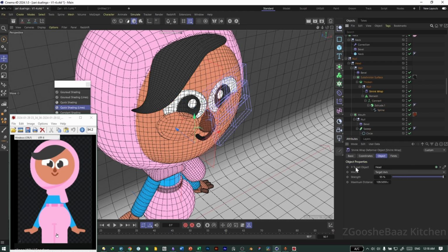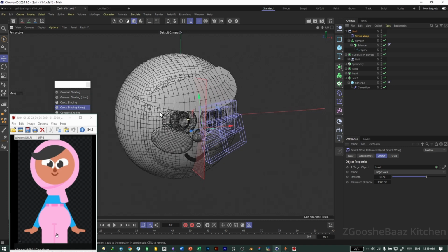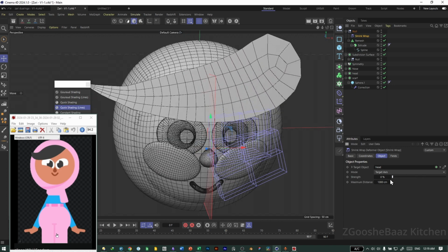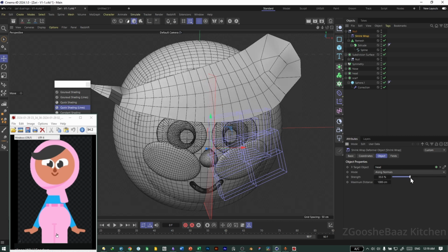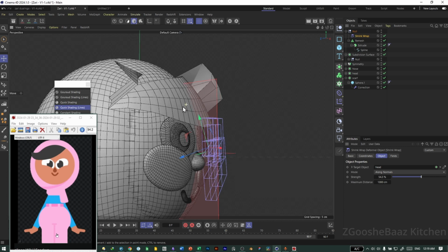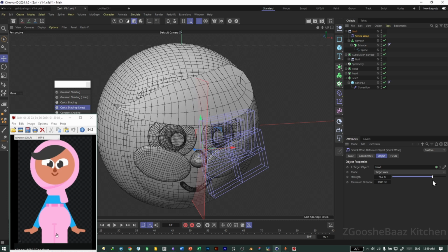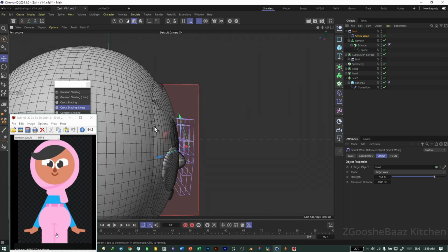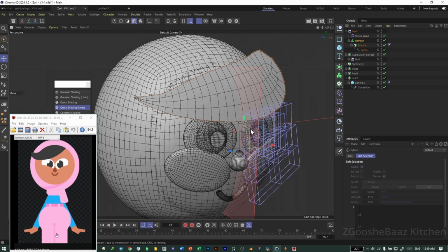Let's see what I used. Tangent axis after image. Let's use tangent. Tangent always works, but the downside is that it will shrink the shape. Normal is better if it works because it will see the normal of this surface and this one to match it and not make it smaller. But tangent works more reliably. We don't want to push it to 100%. This value is okay. Let's push it up a little bit.